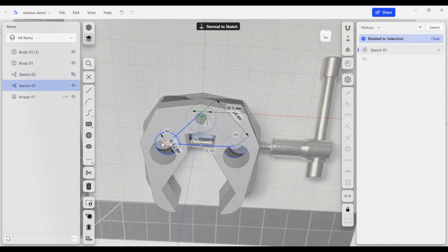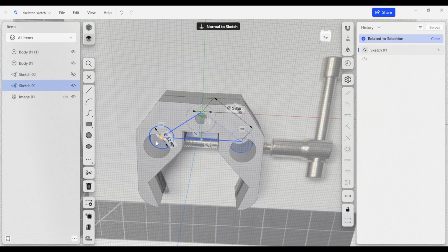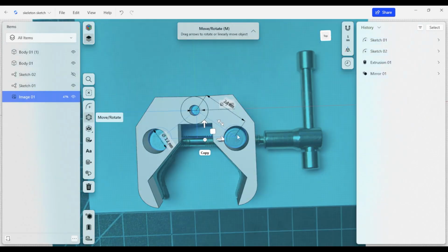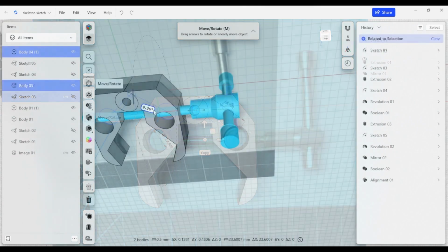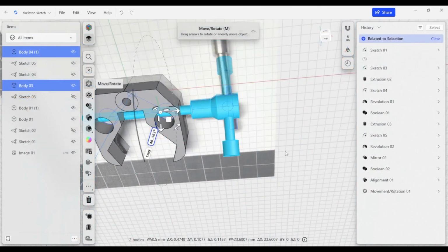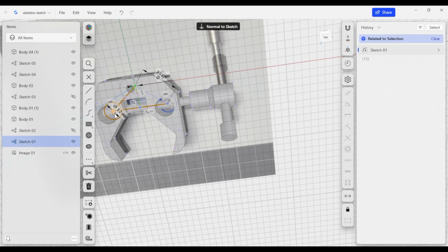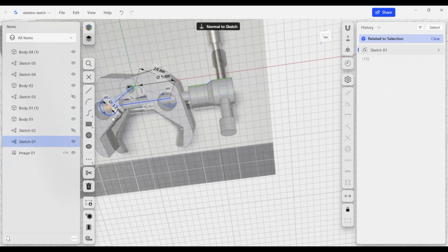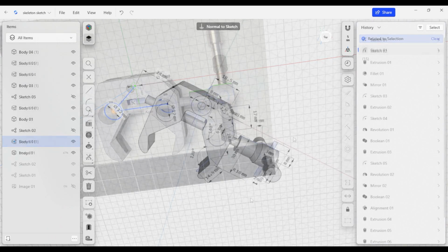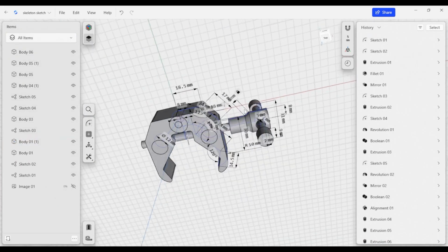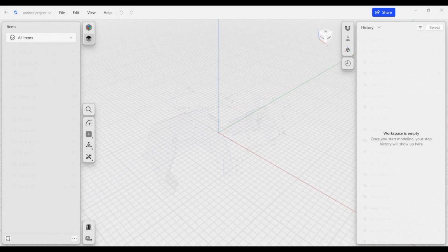While there aren't any explicit assembly features inside of Shaper 3D, we'll use these driving sketches alongside the unique mix of direct modeling and feature history to create a mechanical assembly that we can move around and preview within the workspace. For this tutorial, we're going to recreate a mechanical screw clamp where we'll primarily use sketches and alignment features within Shaper 3D to create a movable model that maintains the relationship between all the components.